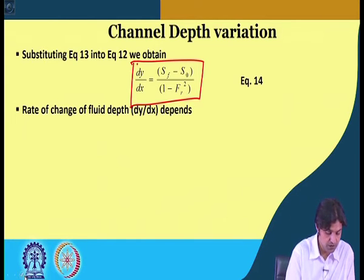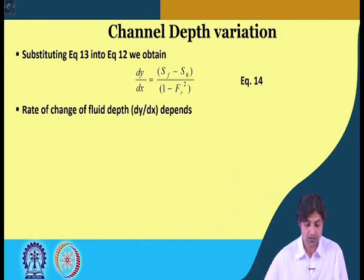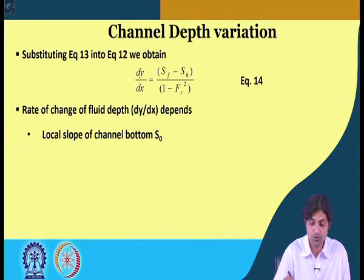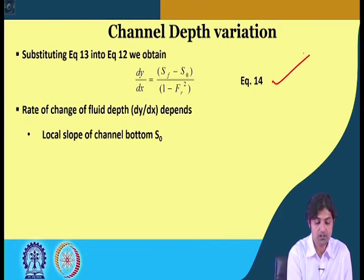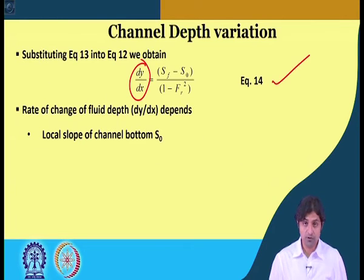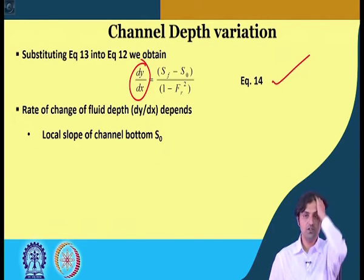So, if you look closely at this equation, the rate of change of fluid depth, dy by dx. If you remember, in the beginning we related all the types of flows, like uniform flow, rapidly varied flow and gradually varied flow, with this value of dy by dx.